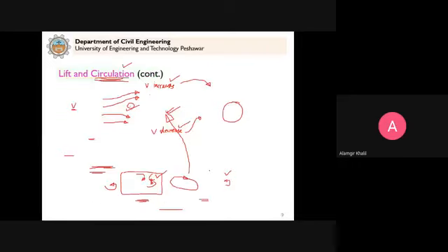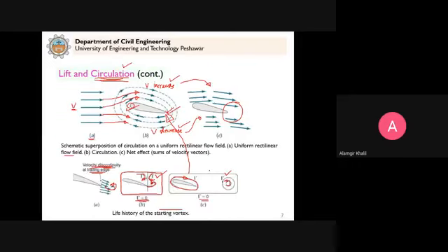So now we try to understand the mechanics behind where this circulation comes from. And remember, this circulation will be on the body as the body moves. For example, this can be the wing of an aeroplane. When the aeroplane starts motion, this circulation will develop, and when it moves through the air, it will result in a velocity difference, then a pressure difference, and then the net force.